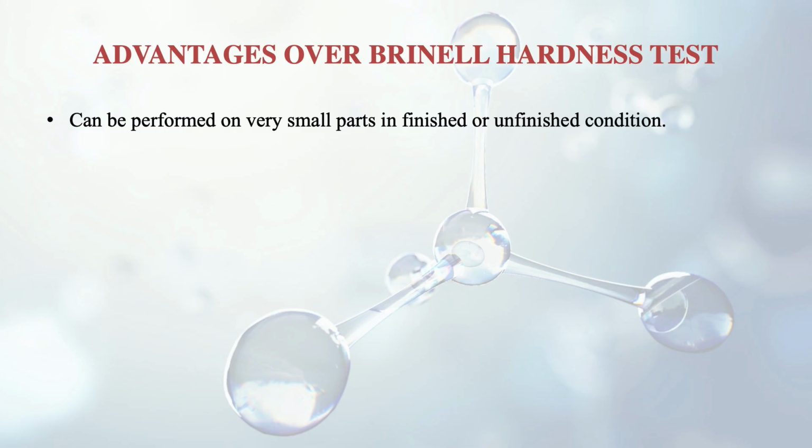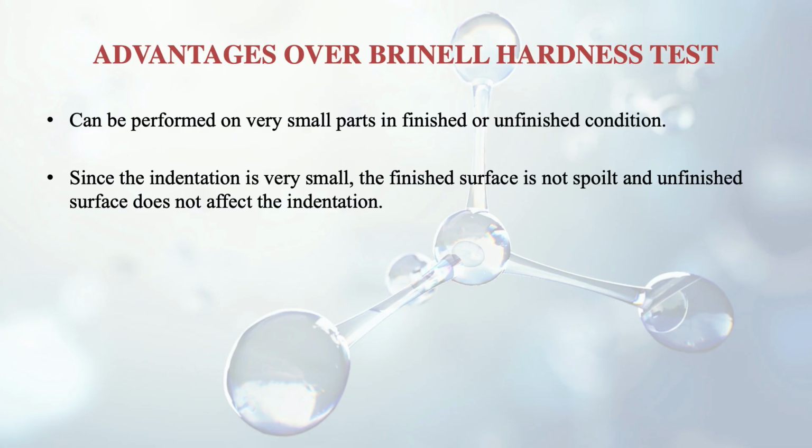So what are the advantages of this Rockwell test over the Brinell hardness test? Here are some of them. It can be performed on very small parts in finished or unfinished condition. So both things are there. It can be in finished or in unfinished condition, and very small parts can be tested also. Since the indentation is very small, the finished surface is not spoiled, and unfinished surface does not affect the indentation.